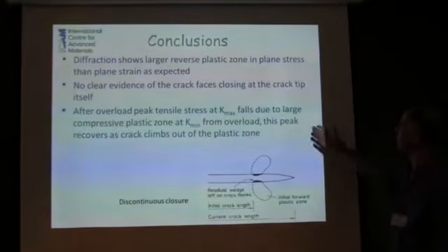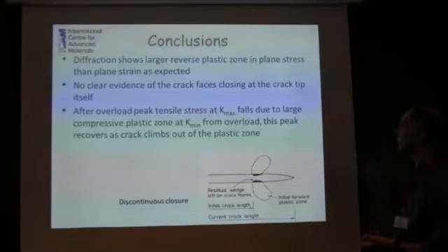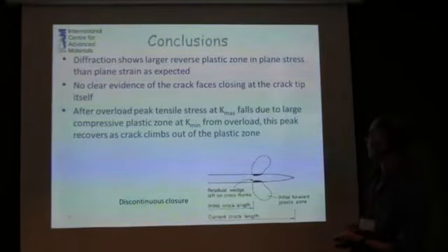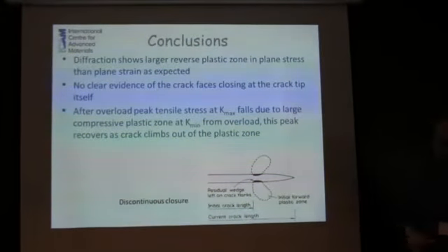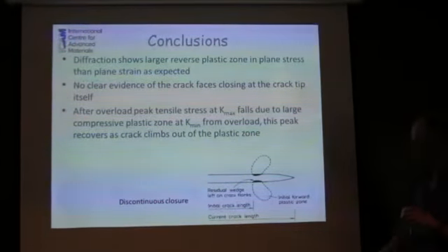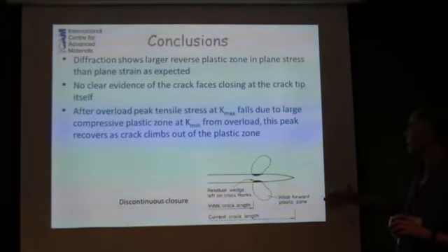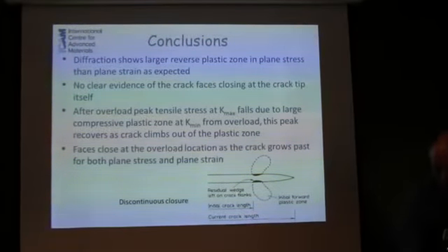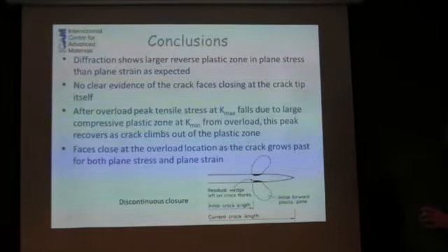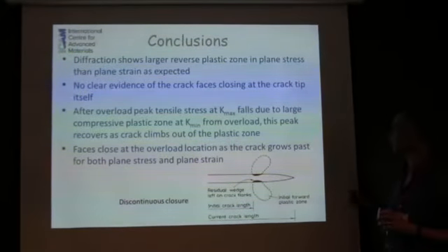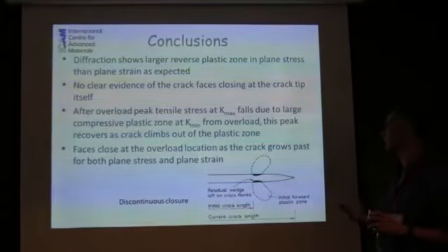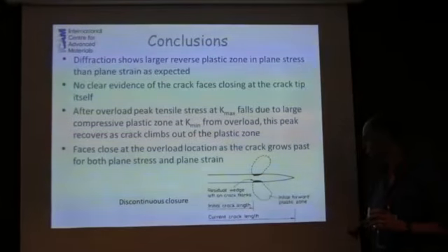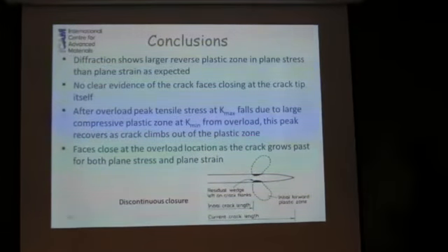After overload, the tensile peak at Kmax falls due to the large compressive zone that came in from the overload, and this peak recovers as the crack climbs out of the plastic zone. So as it climbs out of the overload plastic zone, the Kmax rises. And the faces close at the overload location, so we definitely see some closure, if you like, or crack face loading far away from the crack at the location where you had the overload.